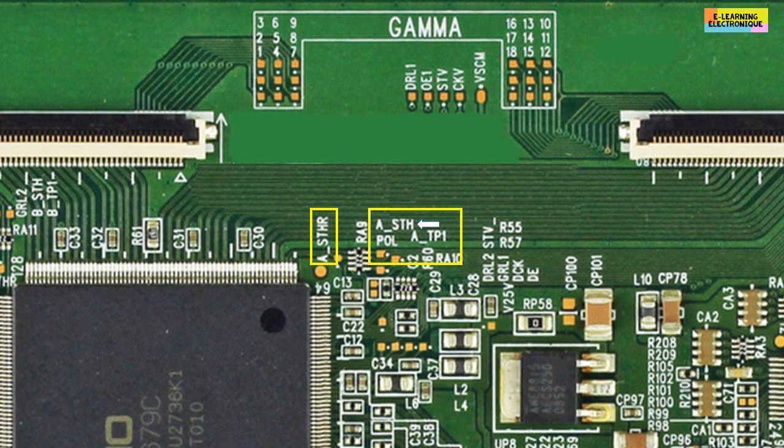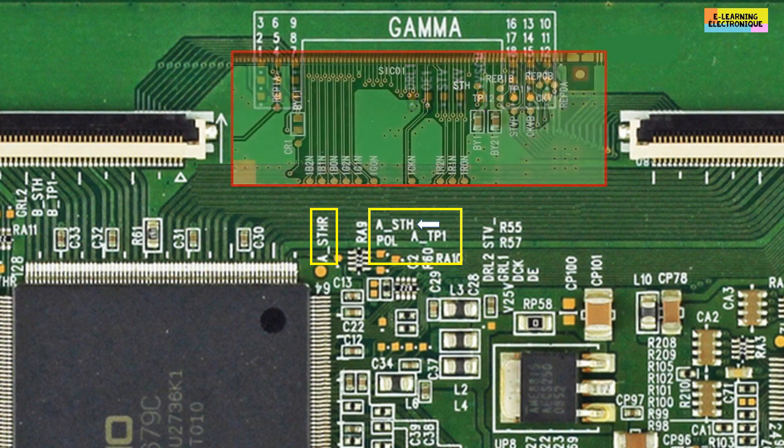For the term TP, it should not be confused with the abbreviation often used to designate the test point of an electronic board, which allows to make measurements of voltages or signal at different places according to the manufacturer's specification. In the case of the source driver, the term TP, which comes from the abbreviation of the words totem pole, designates the latch signal. A number can accompany the TP of the test points when they are numerous.